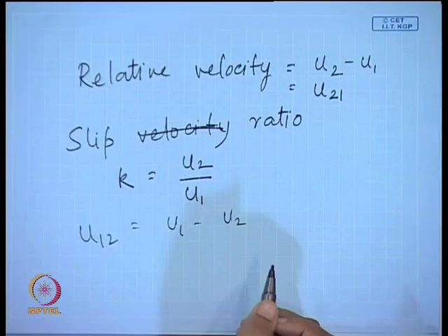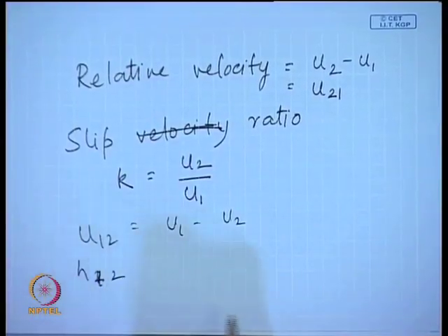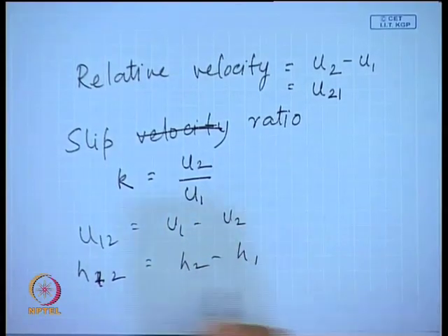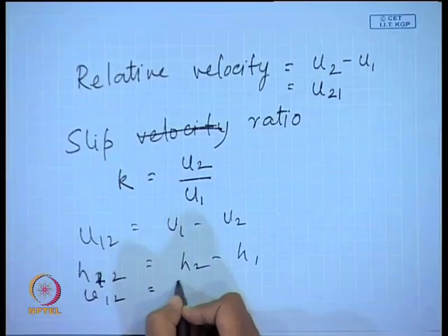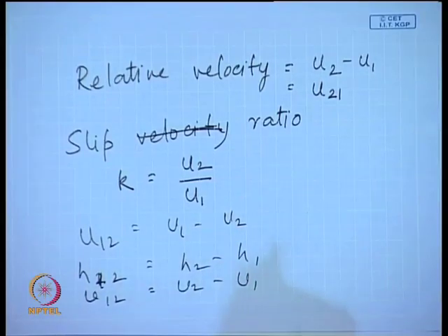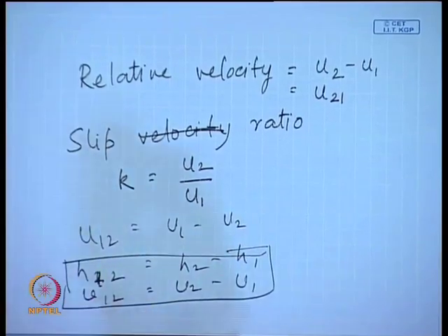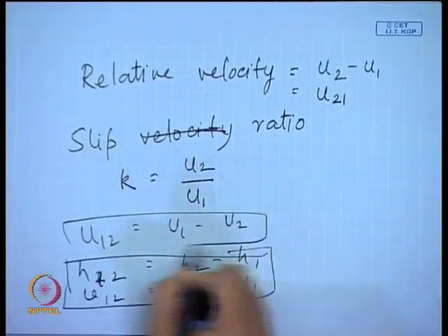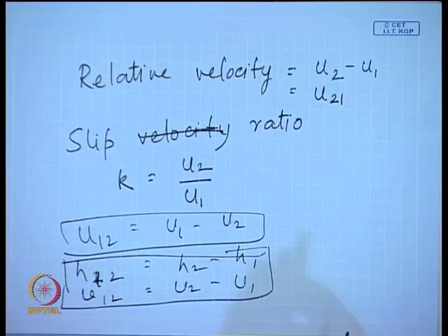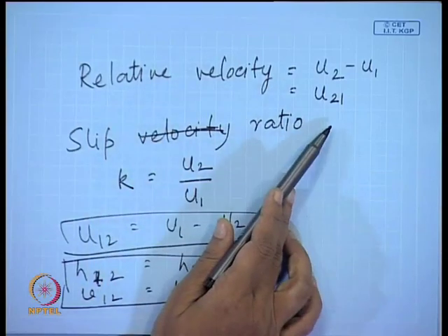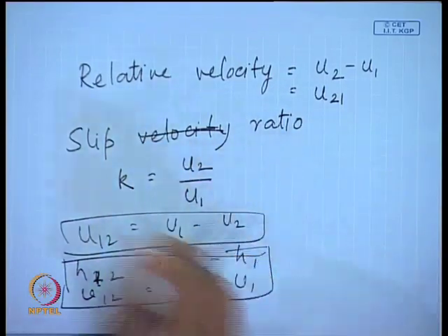But in thermodynamics, if you remember, what does H12 refer to? H2 minus H1. When we say V12, it is V2 minus V1. So, remember one thing, the sign conventions in thermodynamics and in multiphase flow are slightly different. The two other terms which I wanted to define, one is the relative velocity, the other is the slip ratio.